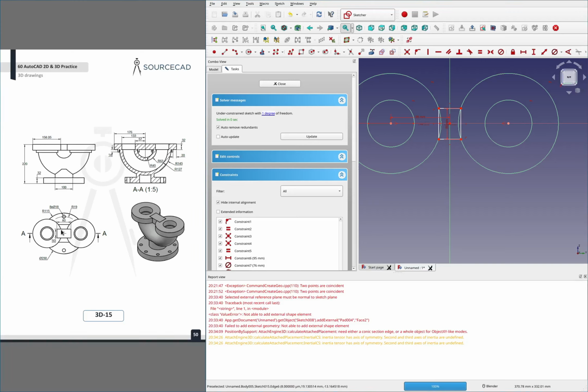I'm not even going to dimension that part, and I'll explain why. Okay, so this 80 here is dimensioning to what? Because this thing is completely flat on top, right? So if you were to manufacture this thing, this little bit here wouldn't exist, right? So there's not really any reason to be dimensioning that, you know? And then I guess we assume that this is in the center line with the circles. But I think that's an okay assumption.